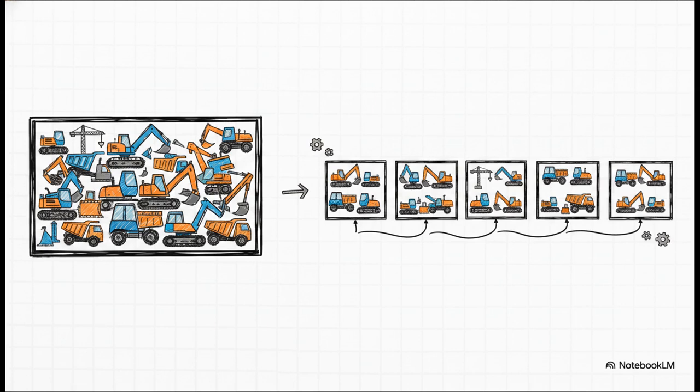So, to solve those very real physical resource constraints, we start with resource loading. That means assigning the required manpower and heavy machinery to our scheduled tasks. But here is the classic problem. What happens when your schedule says you need 5 excavators on Tuesday, but you physically only have 3? Well, that's where resource leveling comes to the rescue. We take that float we calculated earlier and use it to smooth out the demand, shifting non-critical tasks around to solve bottlenecks and prevent our teams from being completely over-allocated.